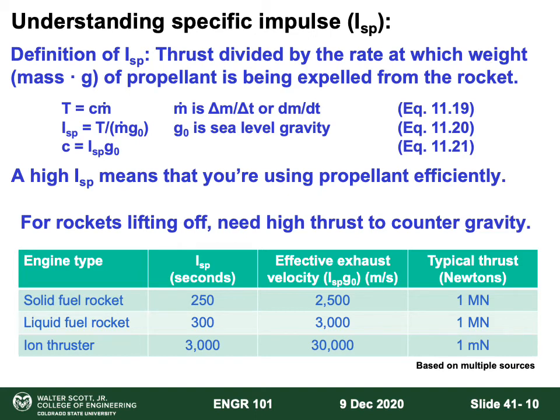There's an alternate technology which would be much more efficient, and that's an ion thruster. You may have heard about those in various different kinds of movies. It's about 10 times more efficient in the way in which it uses fuel, because it exhausts the fuel at much, much higher velocities. But currently, we haven't been able to make them with any really significant amounts of thrust. So where liquid rockets are measured in meganewtons, ion thrusters are measured in millinewtons.